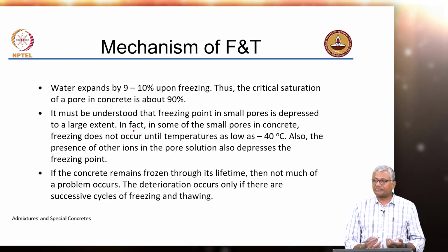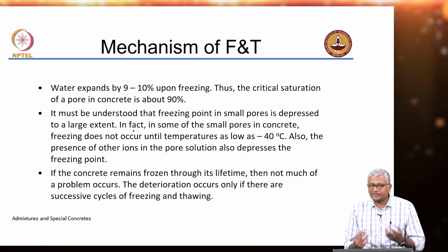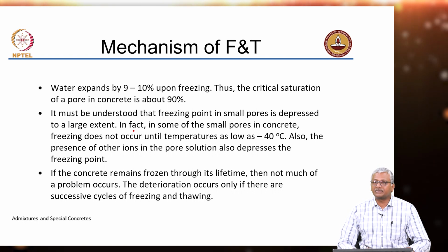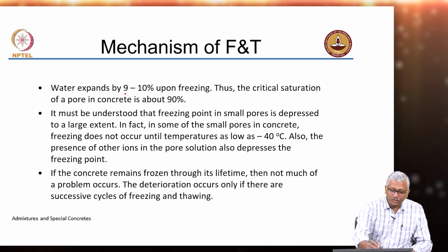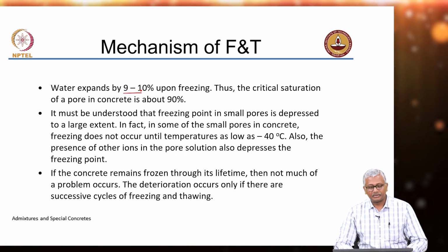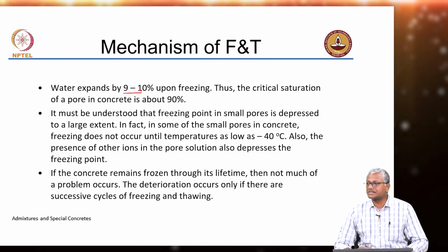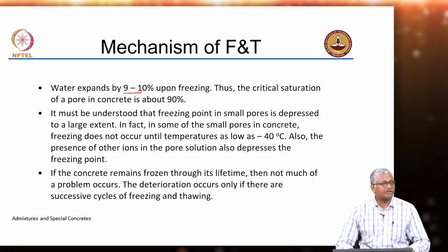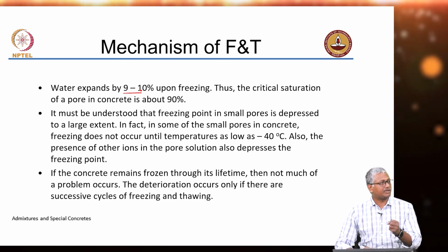So, why is freezing and thawing damage happening? Obviously, water transforms to ice, and the expansion of water upon freezing is 9 to 10%. So, if concrete has a saturation level of more than 90%, that means in freezing conditions, the porosity cannot take up that water.